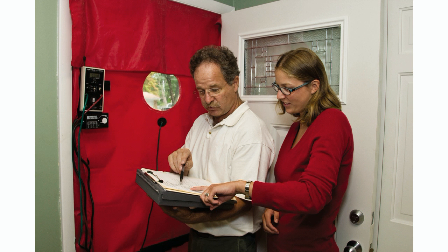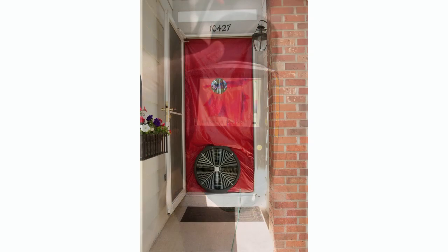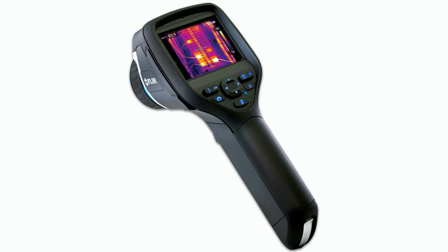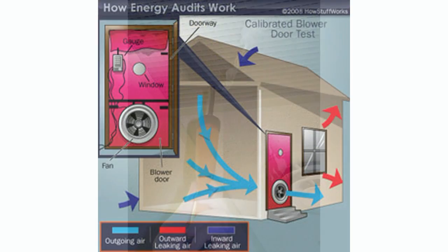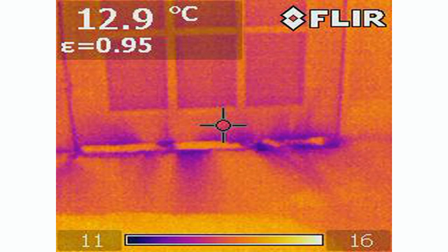We recommend always having your Weatherization Pro Home Performance Professional first measure to determine the actual amount of leakage of your windows and doors using a blower door and an infrared camera and/or air leakage detector or smoke pencil. You should be present during the blower door assessment so you can see where and how much your windows and doors are leaking air and energy.